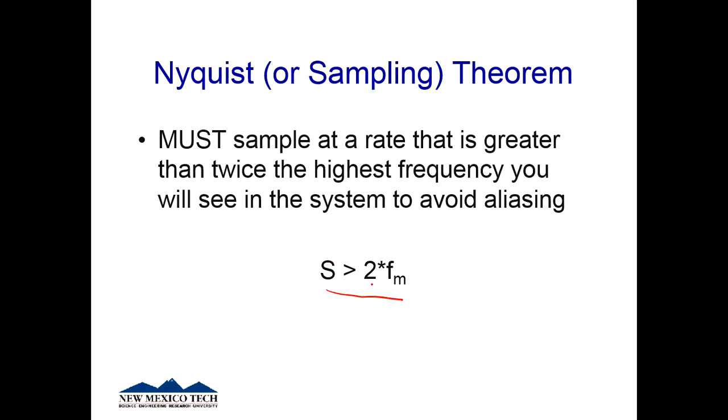Basically you want to sample at least twice the rate of your highest frequency to accurately represent something. And that's just to get the frequency right. If you want the shape to look right and you want it to look like a good graph, the standard advice is at least 5 times, but more like 10 times the sampling rate will help with that. But at least 2 times to get the frequency correct. And so that's basically aliasing in a nutshell.